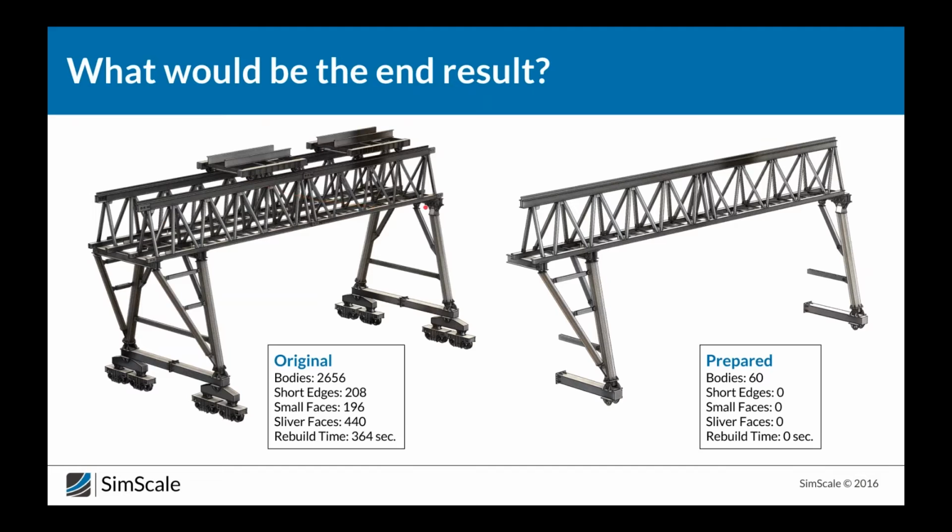So if I was going to use some, say, racking or twisting of the structure, then I would need to model the full structure. Of course, I would model just the half, and once I had defeatured half of it, then I would just apply a mirror operation to then create the full geometry.